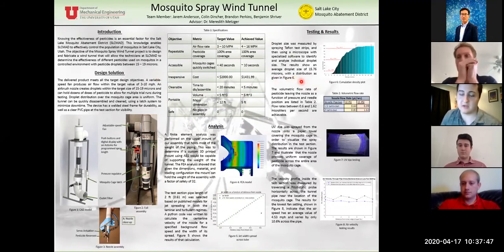So with that in mind, we tested and figured out the volumetric flow rate through the nozzle at 10 and 15 psi, with different needle positions of 1.5 and 2 turns out. These needle positions are what adjust the nozzle to determine how open or closed it is.